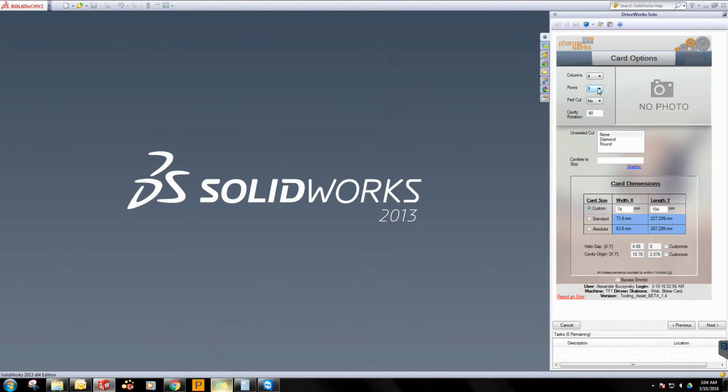Now let's say I went out of the range of what is actually possible. Like we're only allowed 130 millimeters. So let's say this goes up to 152 here. I select this, it'll give me an error and says, hey, your card length exceeds the maximum value. Go over here to customize, I go in and I say, let's say 160. Driveworks won't allow me to do anything about that. If this is a nuisance, we can go and later on in a later revision change that. But as of right now, that's been included just to check that nobody goes above that value.